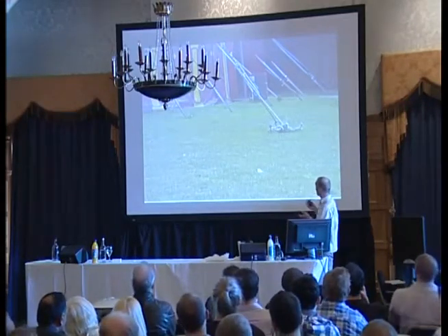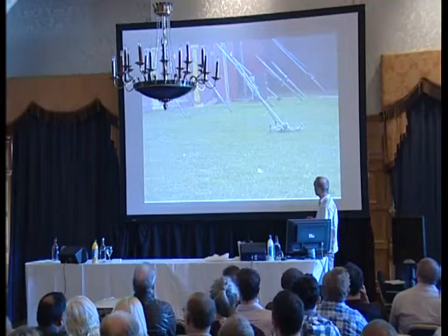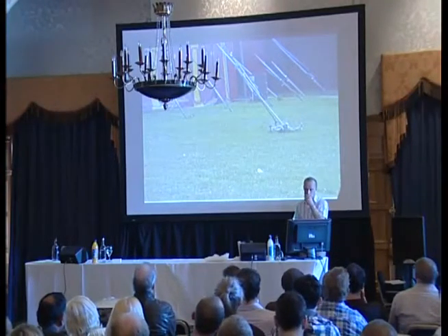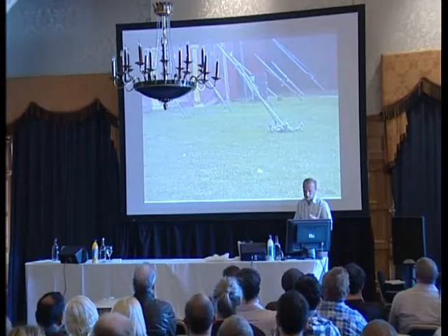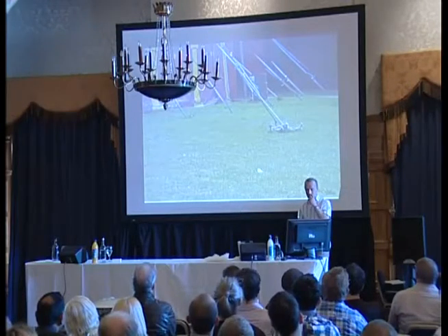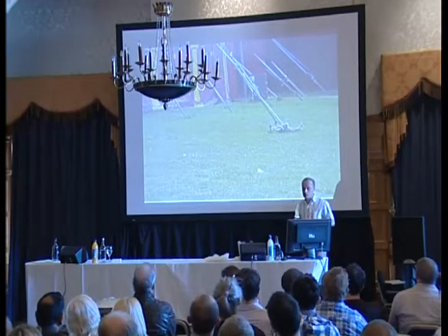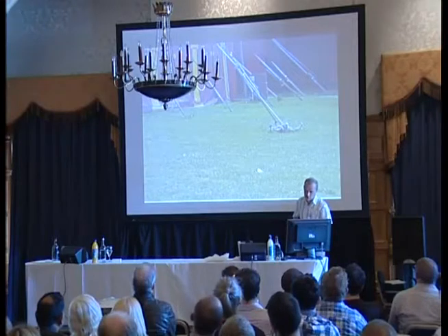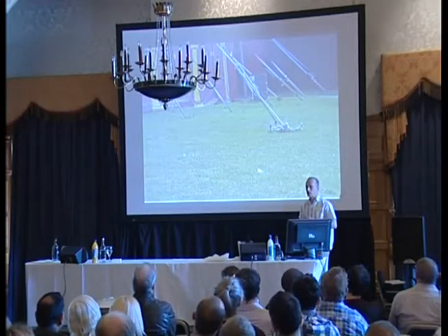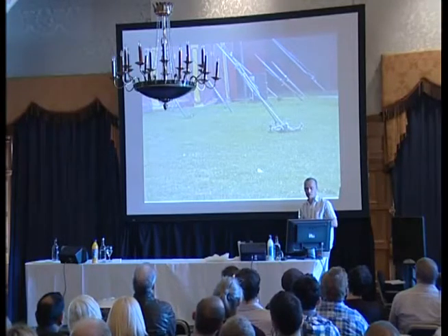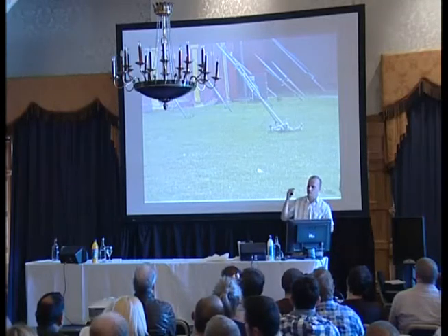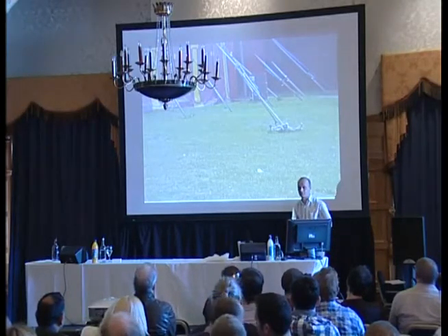But this is a classic example of a big top and it's got 3 stakes in it because it's holding up the king bolts. Yeah? That one looks nice, driven into the ground, looks good. It's an old-fashioned style with the rope around it, but it's got a separate chain on it as well. And that, to me, in my view, is okay as long as one condition is covered, and I'll throw that out to the floor: how can I tell that that's okay? What's the thing that's actually most critical to that?